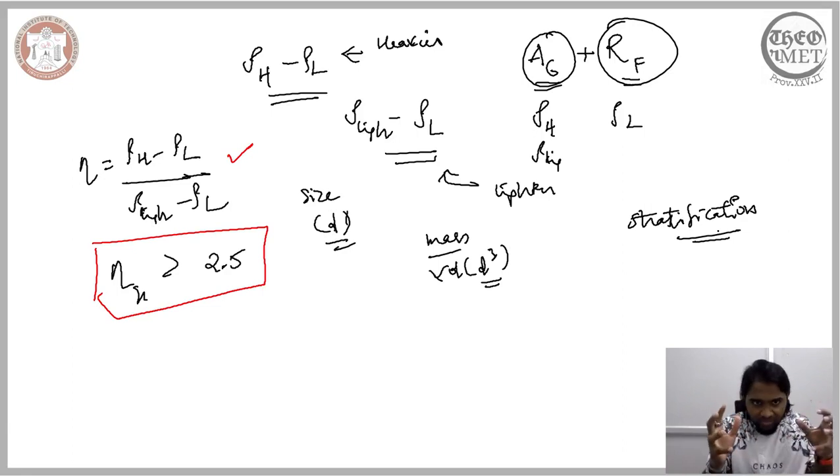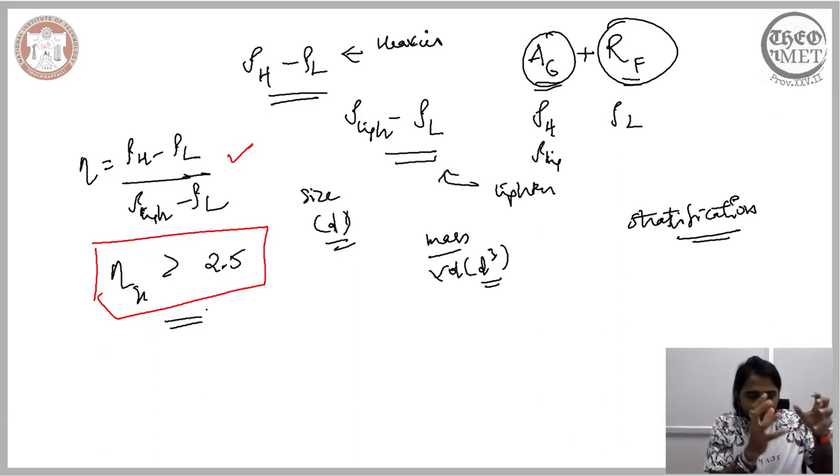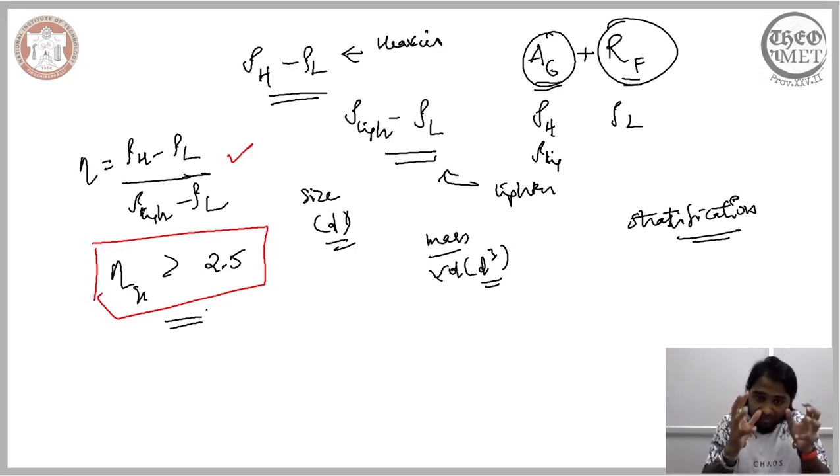That is not considered in this efficiency framework. Even though this simplistic, straightforward expression for efficiency will enable us to understand the efficiency of a given operation, and to choose a specific mixture to be handled through the gravity separation process, we cannot say for sure that all the features that govern the movement of the particles in a given medium are accounted for in this expression. One factor that is missing in this simplistic, go-to expression of the efficiency is that it assumes that the movement of the particle does not depend on the size.